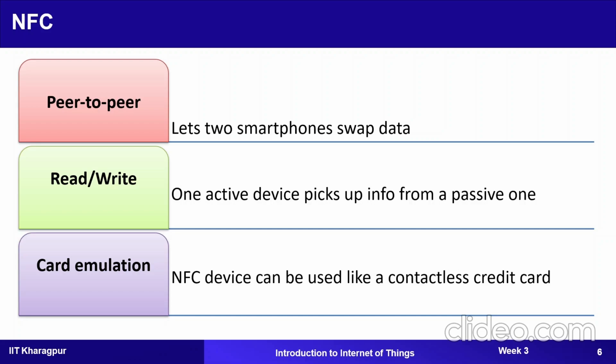The network and transport layer are based on TCP or UDP, and the IP is IPv6. The data link layer supports mesh topology, mesh routing, and frequency hopping, and the physical and MAC layer are based on IEEE 802.15.4. So basically this is also an extension of that standard. The topologies used are star, tree, and mesh topology, and the networks include radio link, ISA over Ethernet, and field buses.